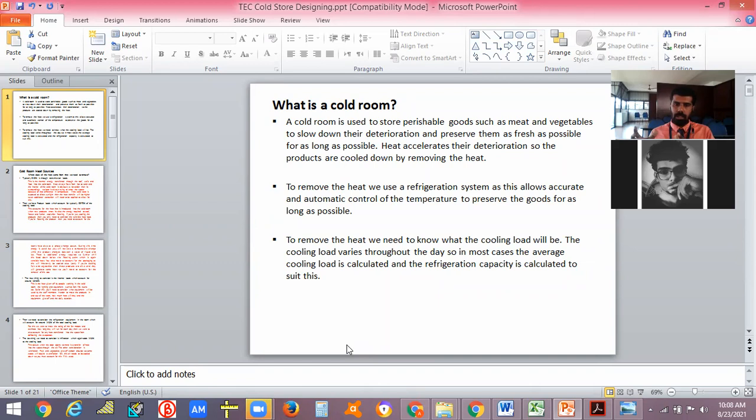different items. It can be the product, it can be some equipment, it can be the wall, roof, floor, etc. And we'll be calculating it, adding it, and converting that amount of heat in BTU per hour to a ton value. That's the usual general method we use for heat load calculation.